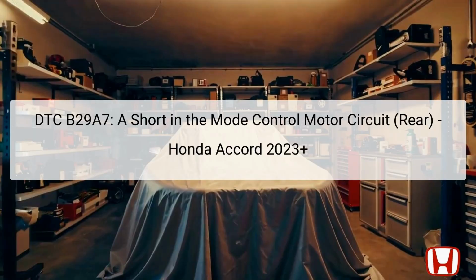Welcome to the troubleshooting guide for the DTC B29A7, which indicates a short in the mode control motor circuit located at the rear of the Honda Accord 2023 Plus. This diagnostic trouble code is triggered when the input voltage from the rear mode control motor is detected as below the specified threshold by the climate control unit.